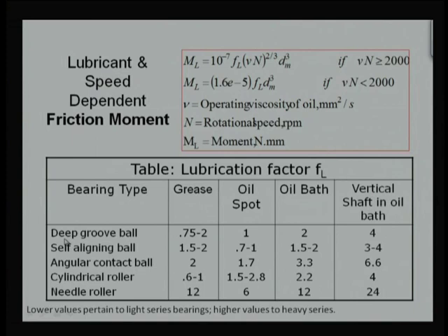Here we are able to see there is a change in bearing. If there is a change in bearing, there is a change in the FL value. Like in this case, deep groove ball bearing versus angular contact bearing, and for angular contact bearing, you are able to see the higher value of FL. It is going to cause a higher friction compared to the deep groove ball bearing, whether it's the case of the grease, the oil spot, the oil bath, or the vertical shaft. In all the cases, angular contact bearing is going to cost more, particularly from the friction point of view.